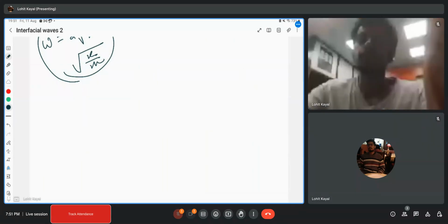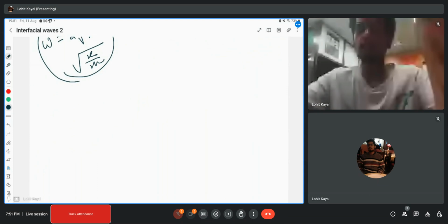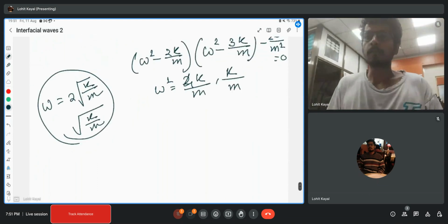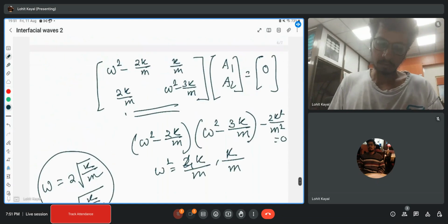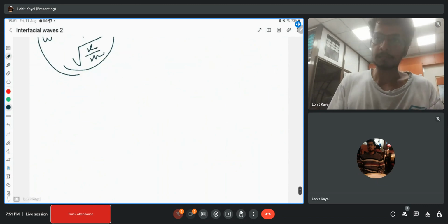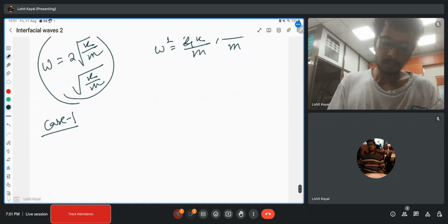Yeah, sorry for the interruption. Alright. So now you need to calculate the modal shape. Okay, you just need to put this formula here. So now let's study case by case. There are two cases. Case one, that is omega square equal to 4k by m.